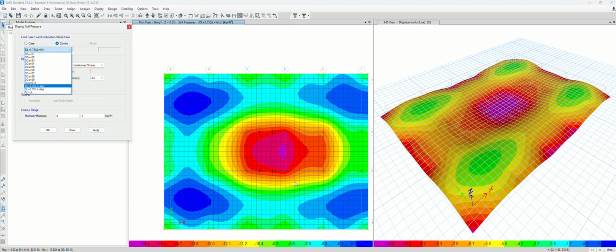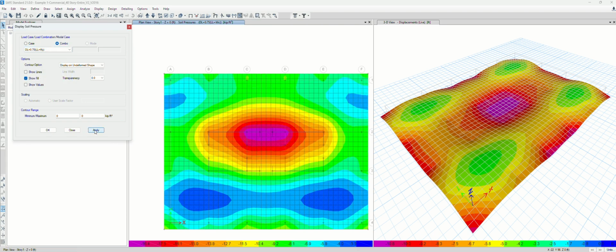So the right side has more compression, or more stress, due to the downward reactions associated with the soil bearing. Wind blowing Y, same thing: gravity effect plus your wind overturning effect makes this downward pressure on the opposite side, right? But still, they're all less than 20 KSF.